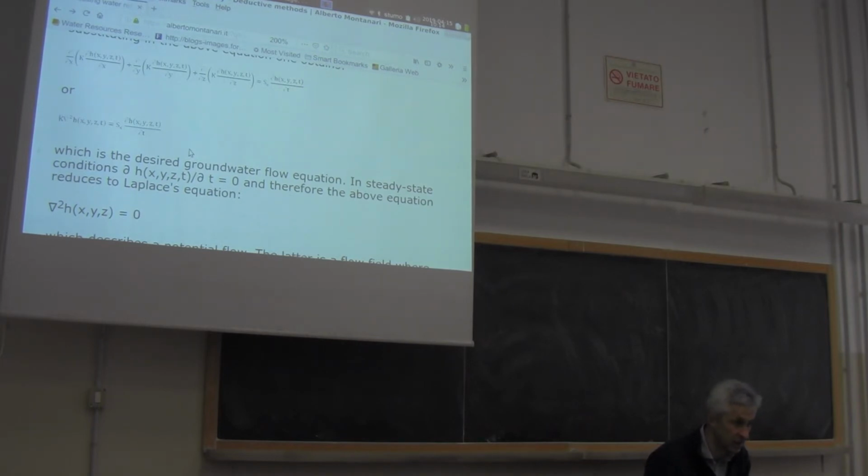In classical groundwater theory, we refer to steady state, and the only parameter of the aquifer that we need to know is the hydraulic conductivity. Hydraulic conductivity is necessary. There is no way out from it. And the volumetric specific storage is something that we need when we want to study changes in time, especially when referring to short times.